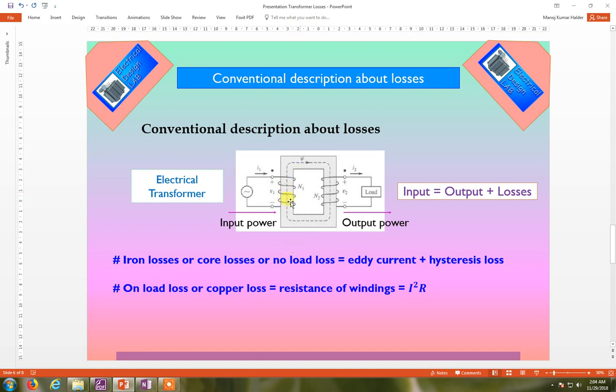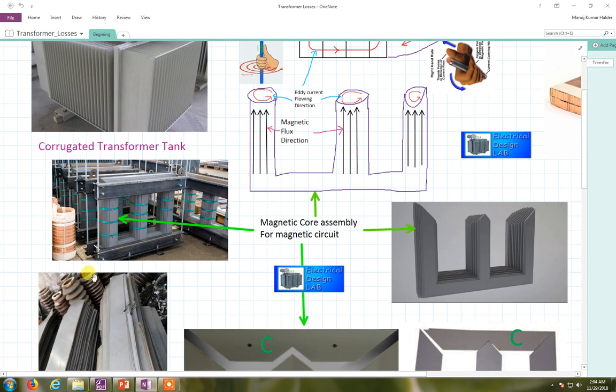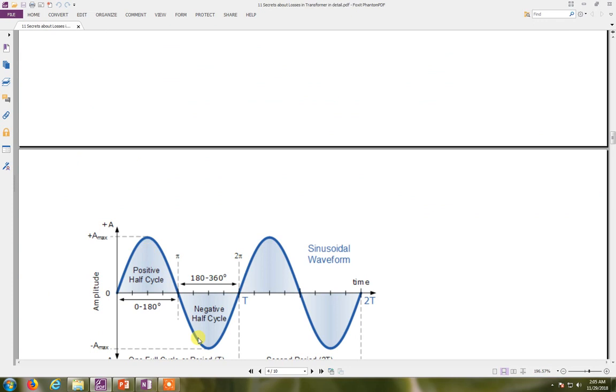Okay, and this is not the only fact, the core is also laminated. You look here, this is the core, and this core is wrapped with insulating cloth. So this will also form a dielectric. So capacitance may occur between the coils, and not only the coils, between the coil and other metal parts. And every time the alternating current changes its direction, the capacitance will also change its polarity, and for this changing polarity some energy is needed, and this energy is used to reverse the polarity.